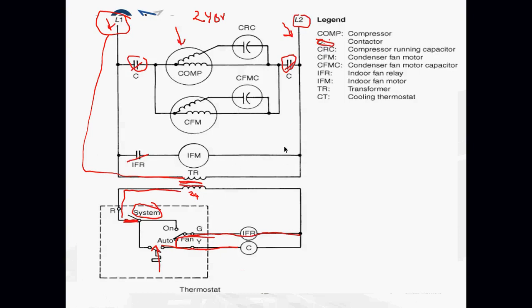This is another one of my pet peeves, and by the way, you guys will see this on equipment in the field. For some reason, certain parts of the equipment don't shut off L2. So even if the equipment is shut down from the thermostat, you might still have power on components. So before you ever reach in there and touch something, make sure it doesn't have power with your meter.